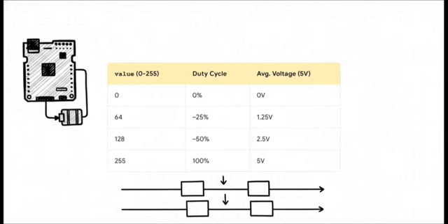When you type analogWrite(pin, value), all you're doing is telling the Arduino two things: which pin you want to use, and what number from 0 to 255 you want loaded into that compare register. It's that simple. If you write analogWrite(9, 0), you get a 0% duty cycle. The pin is always off. If you write analogWrite(9, 128), you get pretty much exactly a 50% duty cycle. And analogWrite(9, 255) gives you a 100% duty cycle. The pin is always on. The Arduino's hardware handles all that high-speed counting and comparing for you. All you have to do is give it a single number.